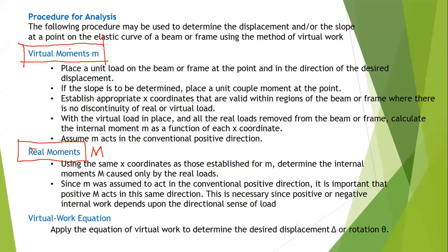Now, once you have set up the equations for virtual moments and the equations for real moments, that's the time that you will use the virtual work equation to determine the displacement or the rotation.